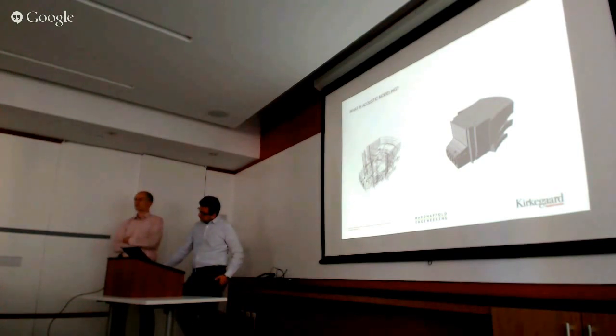Because the Revit to acoustic model transformation doesn't tend to work as well, because we're interested in different things in the model, right? For a large surface with a lot of detail, maybe we can approximate that by giving it some scattering coefficient. But what we do need is for the model at the end of the day to seal airtight. And I think it's the same thing for energy too, because we're interested in how the energy transfers around in that room. That really needs to happen. It's usually just a more efficient use of time and effort to build it from scratch and know that it performs the way that we need it to perform.